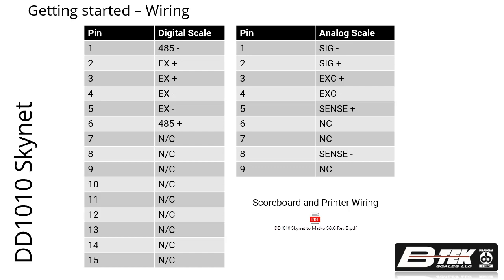Continue to install a printer cable into the top COM port number 4. Use a DB9 male and a DB25 male connector for the printer connection. You must use 3 wires for handshaking. Use pins 2 to 2, 3 to 3, and 5 to 7. Also, make sure to turn on switch 3 on the printer.